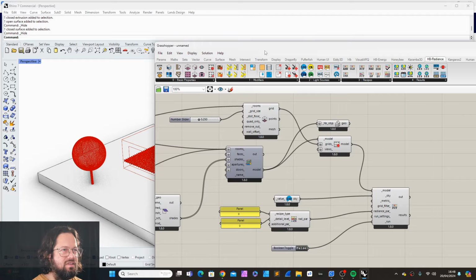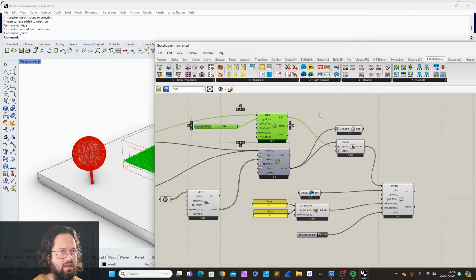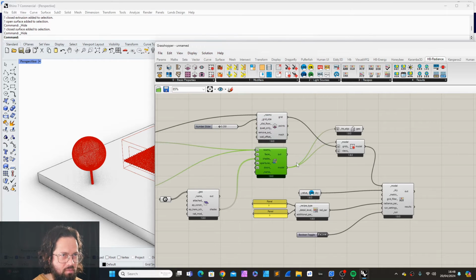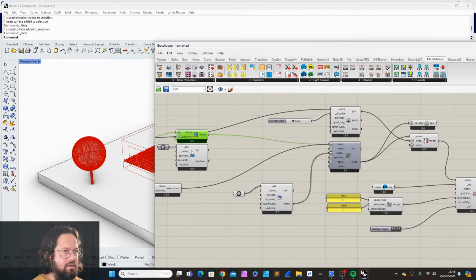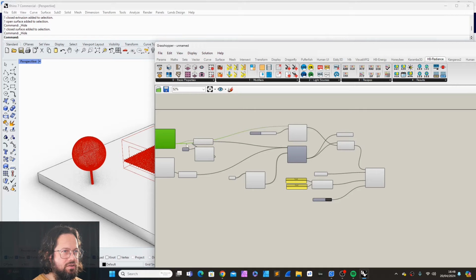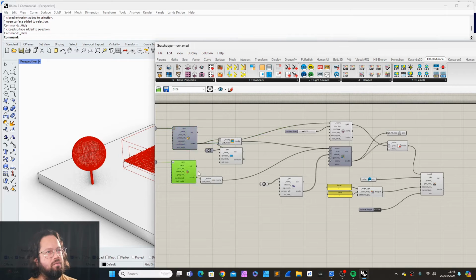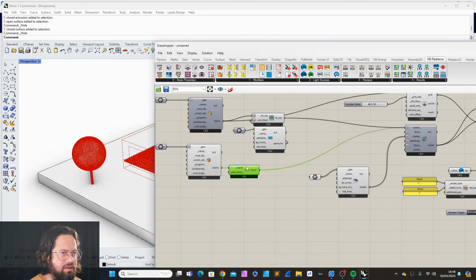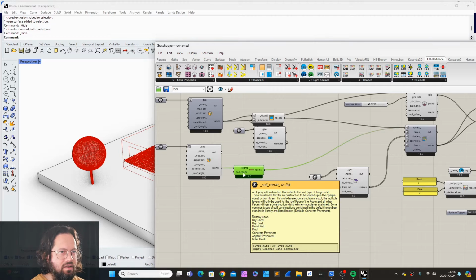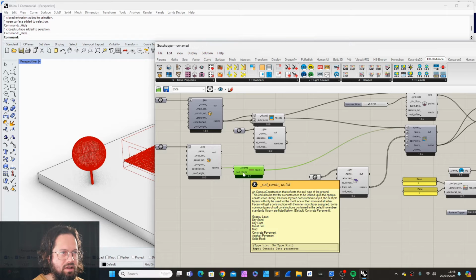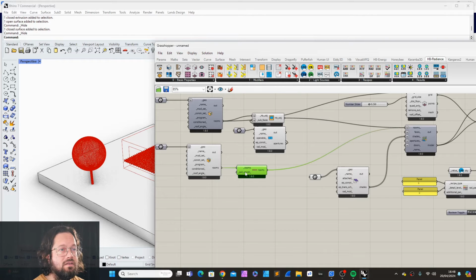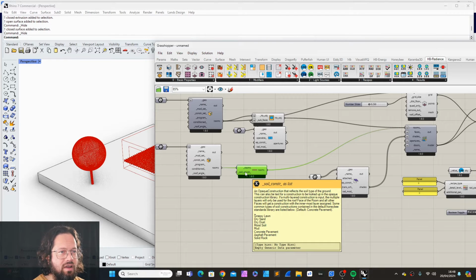Just for better understanding, we created our Honeybee model where we have applied shading. We also applied the apertures to the rooms first. So we created rooms first. We created a room also for the ground level. Then we declared this as a ground level. We can also specify what type that ground material is. In here it says grassy lawn, dry sand, and so on.